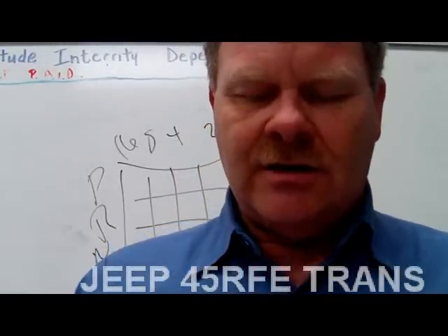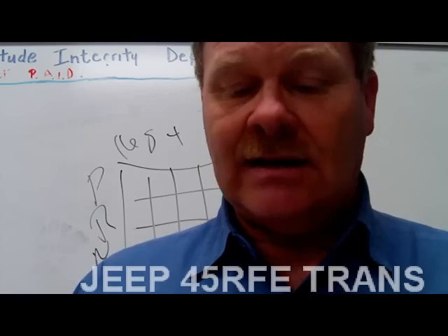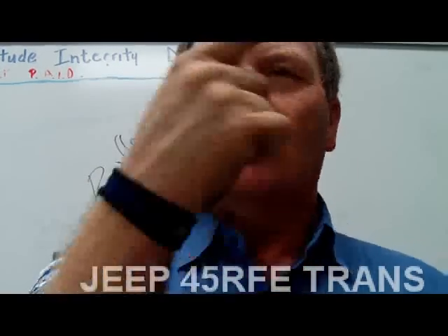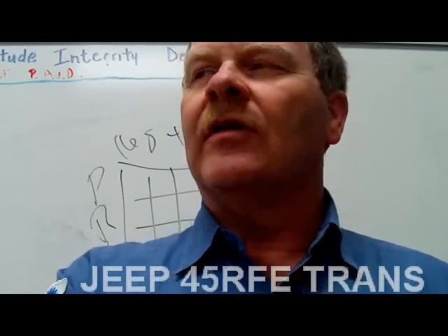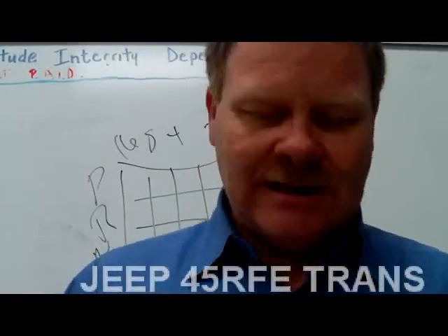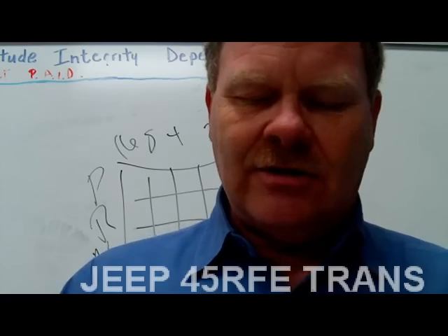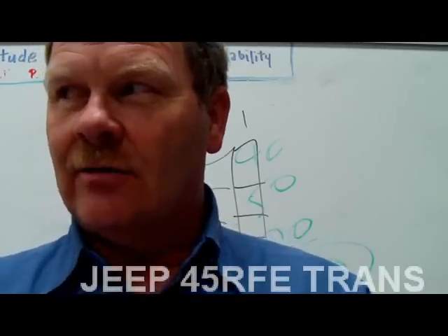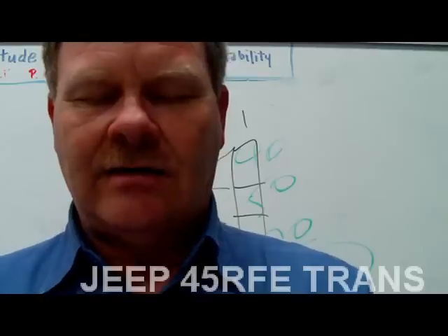The brake switch state is another indirect input, and the TCM engages or disengages the torque converter clutch when the brakes are applied. So if you want to see if your torque converter clutch is engaged, you can watch your tach and keep your foot where it is on the gas. If you reach over with your other foot and tap the brake and the RPM jumps up a little bit, see how that works? The brake switch state is what does that. And it adjusts the transmission shift schedule when the vehicle speed control system's on. See, that schedule is different with speed control on. That's what we're learning here. It's also an indirect input.